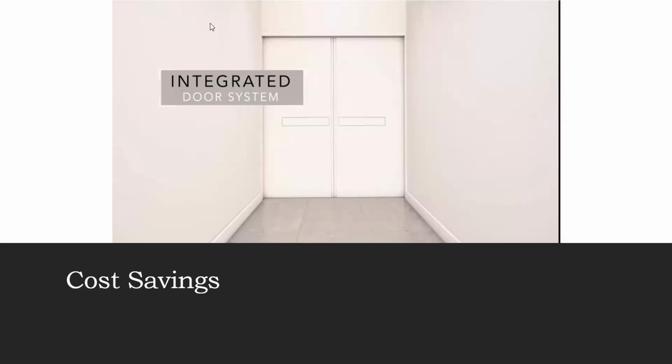So don't pay for a fire door that comes with extra pieces and components but doesn't have all the necessary certifications. What I'm going to drive today is that complete code compliance. This is right before our poll question, but just something in general: integrated door systems are going to be tested to over 1 million cycles. But a lot of the components that would come on a conventional door are only going to be tested to maybe about 100,000 cycles.